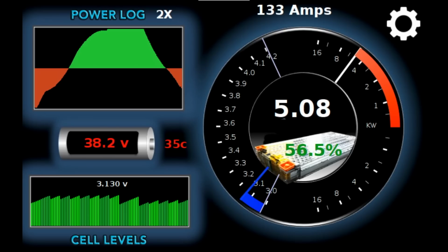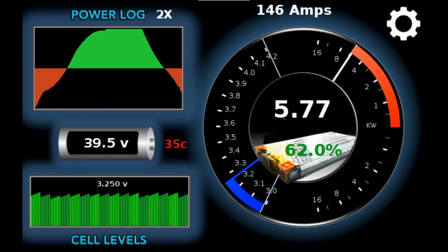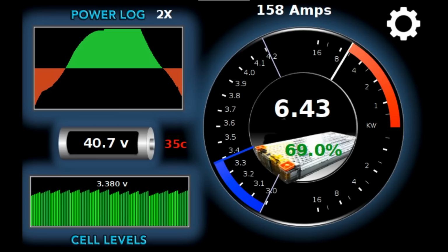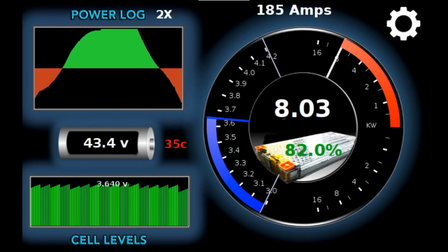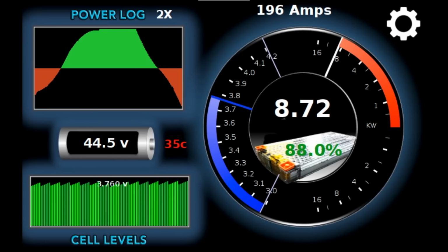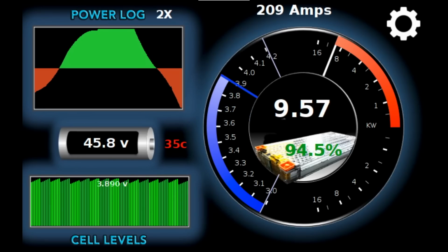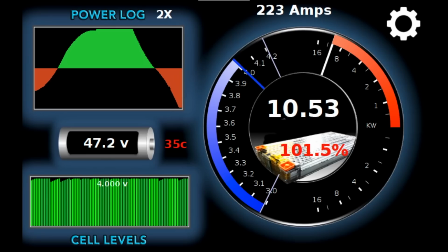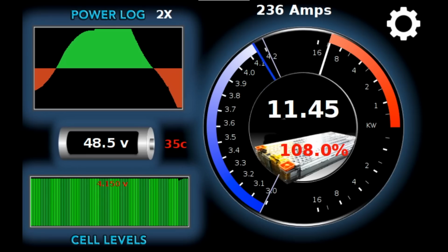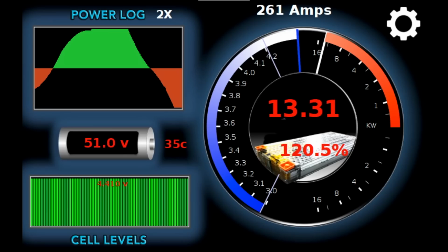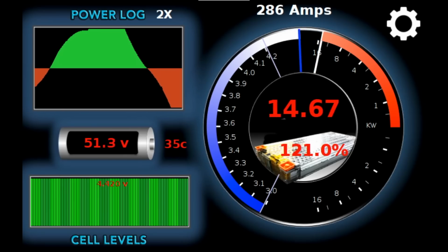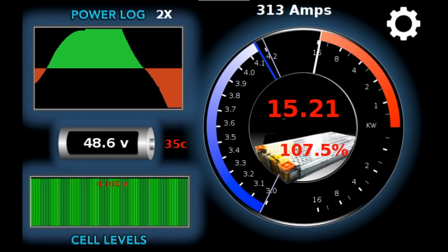And so in operation during the day, you can actually watch cloud activity as you're charging, and this goes up and down based on your loads, but also simply the amount of sun falling on our SolarEdge grid tied inverter segments, panel segments, and this actually makes a little map of what's going on. And similarly at night, you can watch it discharging. You can see the refrigerator come on, and loads increase, and you get a little bit of a bump in the demand on the discharge side.